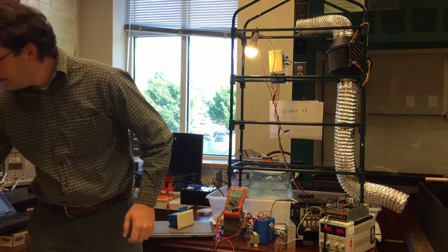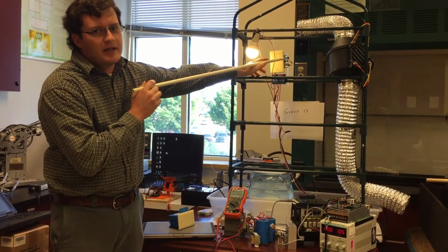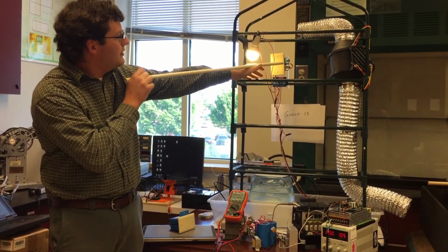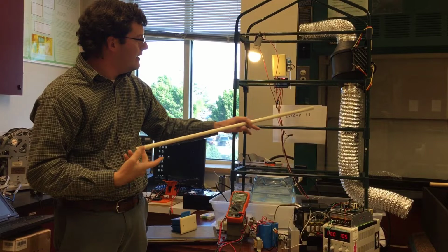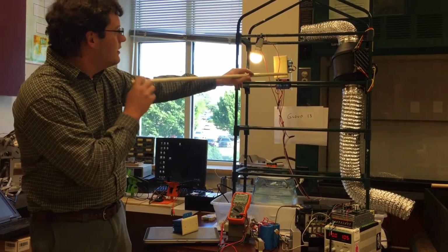And then I'll get my pipe here, put it up close to the humidity sensor here and blow on it. That'll just make sure that the temperature comes up and the humidity also comes up. So what'll happen is the fan is going to turn off and also the humidifier should turn off, because most of them depend on that. So here goes nothing.